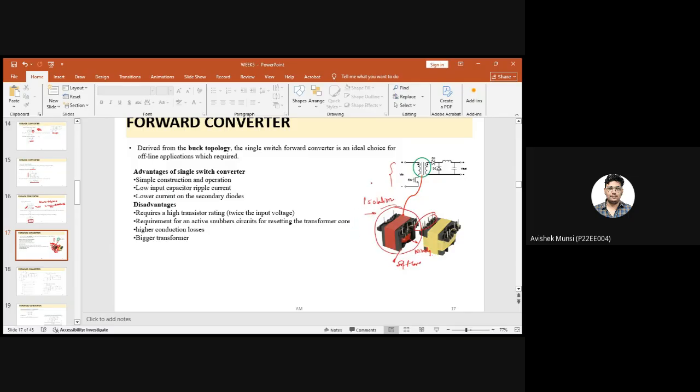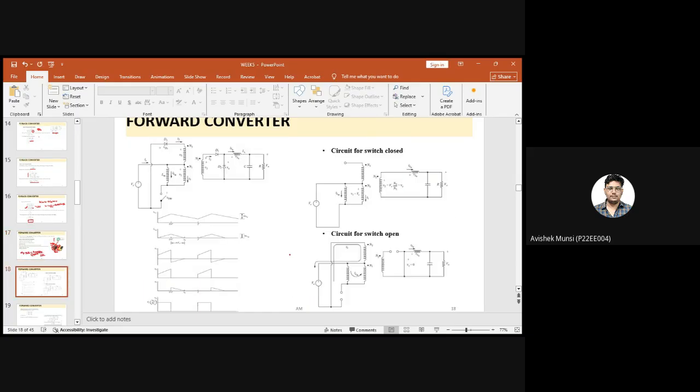Okay, but if you see the chargers, mostly the DC to DC chargers basically use an isolated type of topology. Most chargers mostly use flyback. Presently, the Apple and other chargers are made up of the LLC type of converter. It's a different topology, but mostly they use an isolated topology for making the charging circuit. Okay.